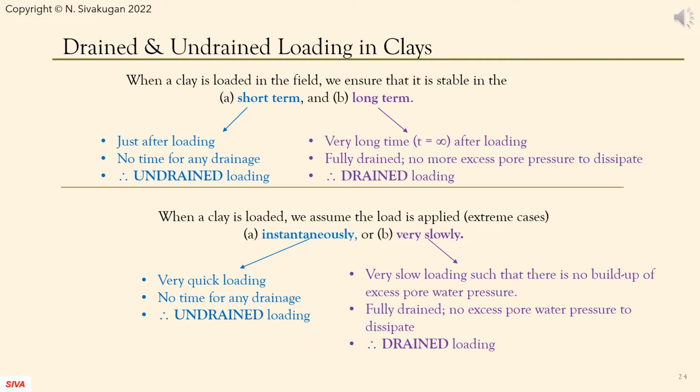It is very important to understand the significance of drained and undrained loading in clays. After a long time since loading or when the loading is very slow, there is no excess pore water pressure and the clay is fully drained. With the effective stresses determined relatively easily, it is possible to carry out the analysis in terms of effective stresses, using C' and Phi'. Immediately after loading or when the loading is sudden, there is buildup of excess pore water pressure and the effective stresses are unknown. Here, we do a total stress analysis, using Cu, and Phi-u equals 0. We are not separating the soil grains and water and treat the soil as one material.